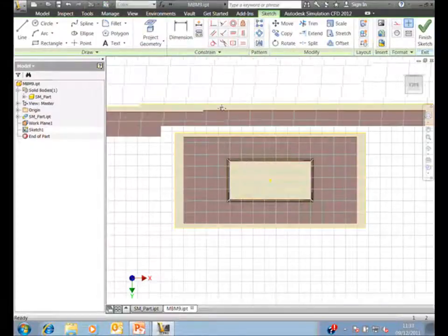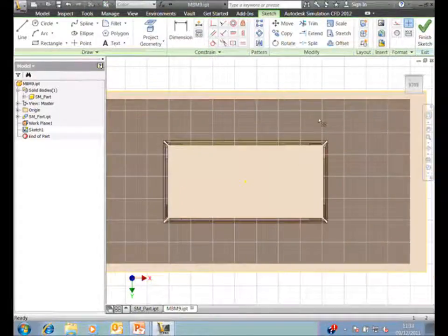And we'll start building some blocks that are going to be bolted to a bolster eventually, that are going to nestle around the flanges of this sheet metal part, so that when the press tool comes down within the sheet metal part here, it presses the flanges down around the blocks that I'm about to model.